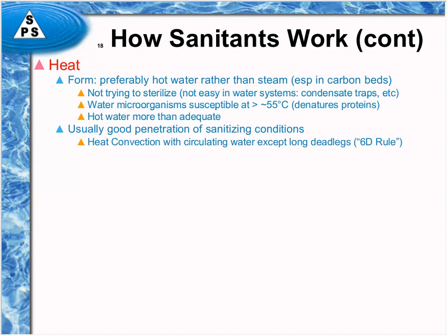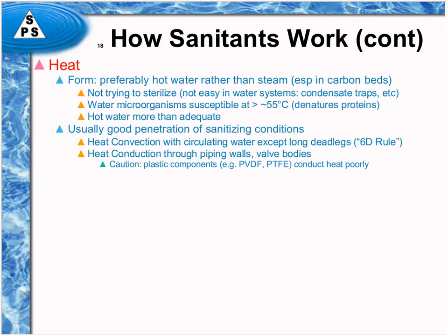It doesn't apply. Also, you get conduction of the heat through the metal piping and the valve bodies, because they're all metal, and so the heat that's conveyed into the piping from the hot water then conducts itself into distal places that might be damp. Be careful if you have a plastic system, because heated plastic systems are usually made out of PVDF or PTFE.